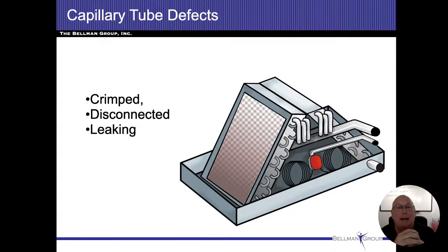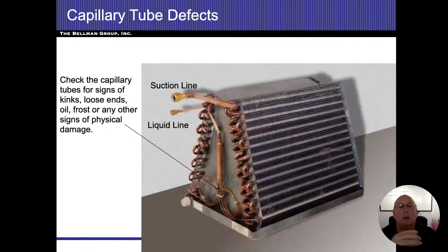So if we ever get inside, and sometimes you'll see a panel on the indoor coils, so you could pull that panel off. Sometimes you can see it when you remove the humidifier, and you can look for these coils. Typically, we don't find too much going on with them. But if they're leaking, and you'll see that with signs of oil, but we wouldn't get our temperature changes anyway, or dented or damaged in any way, we should photograph them and document that as well.